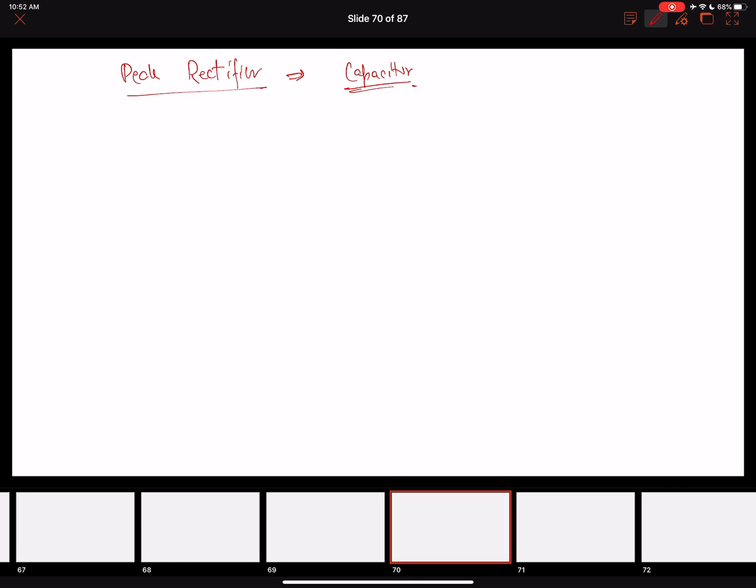All right, so let's do that. Let's do that circuit now, and the circuit is pretty simple. So we have over here, this is our input voltage, this is our diode, and here's our capacitor, and this is our V naught. So let's assume that this is your rectifier circuit. So whenever there's a diode, it's going to rectify the VI.